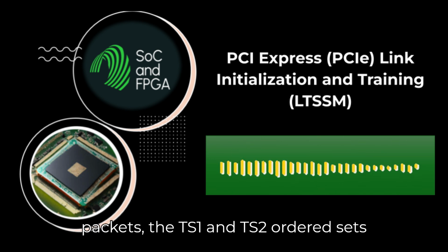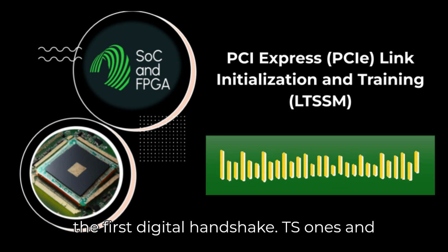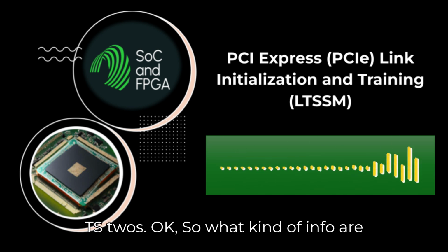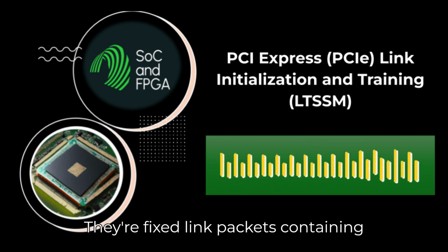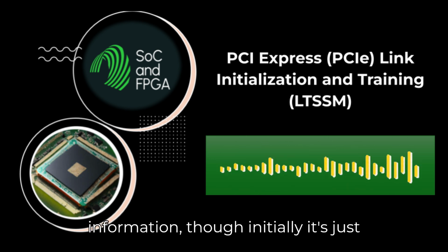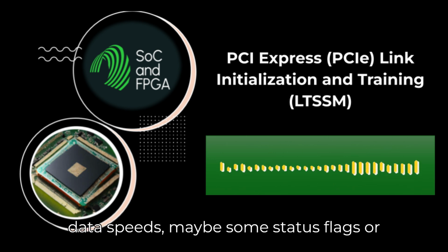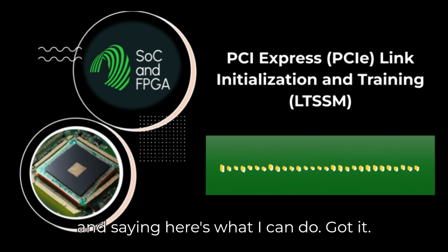This is where those packets, the TS1 and TS2 ordered sets, first come into play. Think of them as the first digital handshake. TS1s and TS2s. Okay, so what kind of info are they exchanging in this handshake? They're fixed-length packets containing essential stuff, like the link and lane information, though initially it's just placeholder values, their supported data speeds, maybe some status flags or requests. It's like introducing yourself and saying, here's what I can do.